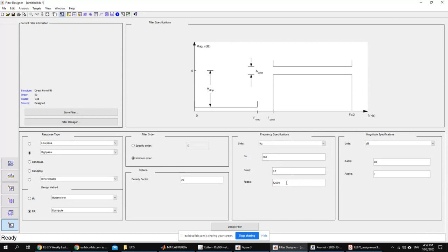Okay, and I can make the f-pass anything above that. So if I'm not worried about the ECG, and if I'm sure that my signal doesn't have very low frequencies, I can maybe choose that as 1. The advantage of using that as 1 instead of 0.5 is that the transition region here between the f-pass and the f-stop will be a little bit wider. The wider this becomes, the smaller the order of the filter will be. We will try that now, okay?